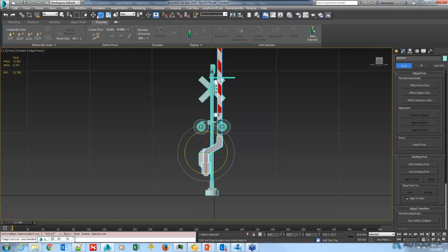So number 1, we're in rotate. Angle snaps on. I could slide this out to 120. If you have a lot of frames, this gets kind of tricky, but you can just come over here to this box and just say 120. It'll move it. I want to make sure I am in animation mode, and that's it.